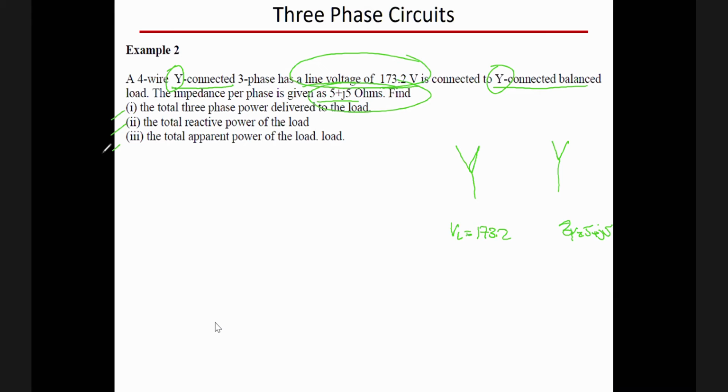My advice to you, use phase quantities whenever you can in power calculations. So find the phase voltage and phase current for the Y load connection here. So how can we find the V phase and I phase at the load? What do you think? Divide by square root of 3. The voltage. That's okay, good point. The phase voltage will be.